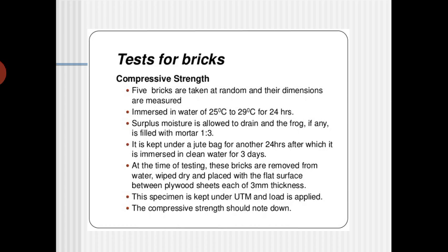Take 5 bricks at random. Suppose you are using one lorry of bricks, don't consider them in a series, you consider them at random. And when you select those random bricks, first your job is to determine the dimensions of each of the bricks.